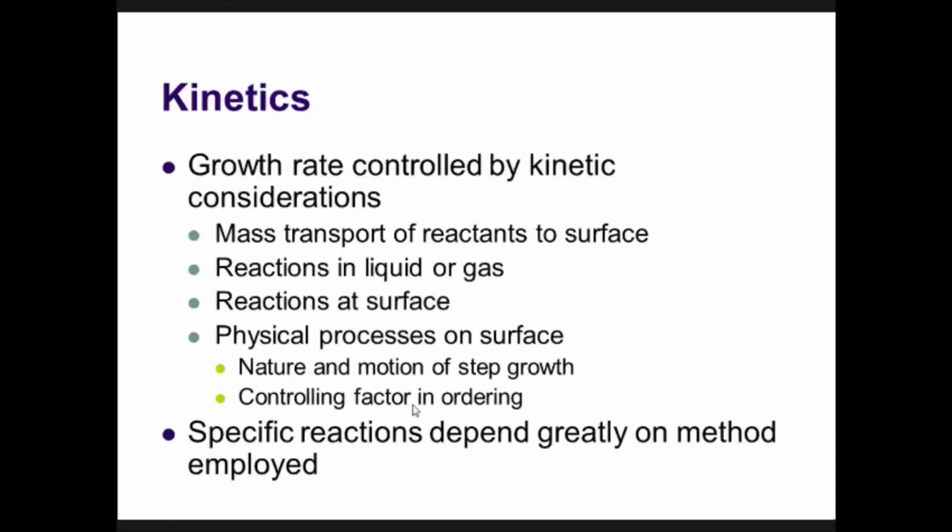So when you consider the kinetics of vapor phase epitaxy, the growth rate is controlled by kinetic considerations like mass transport of reactants to the surface. One has to understand a lot about the growth-rate controlling parameters in MOVPE, because unless you understand the real controlling parameters, you will not be able to achieve the conditions for getting a lattice-matched device structure.